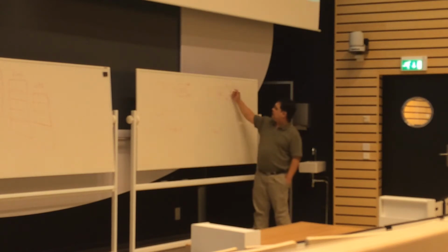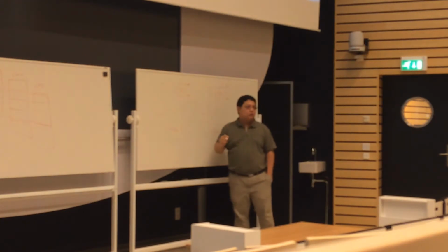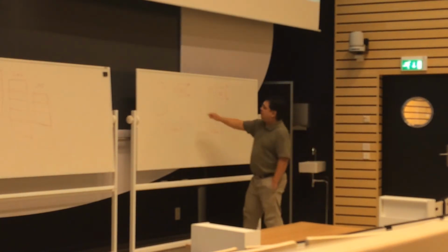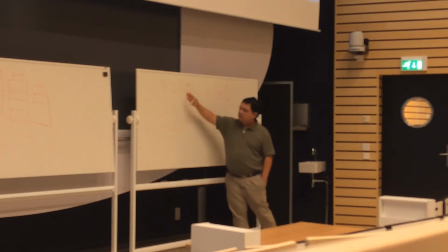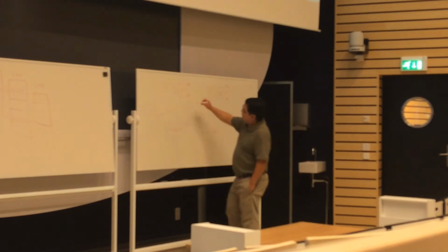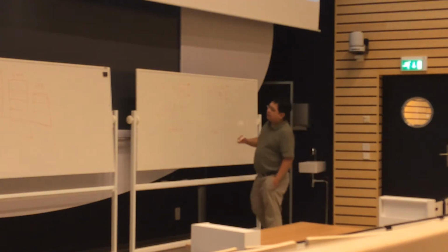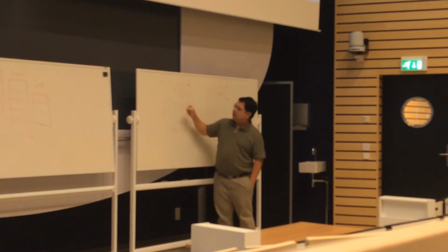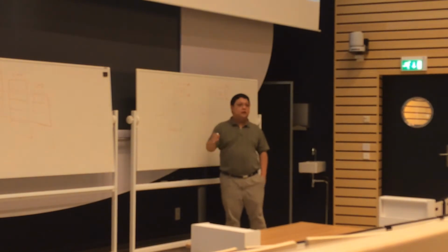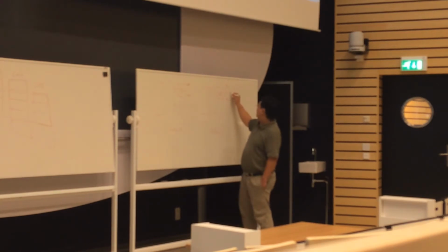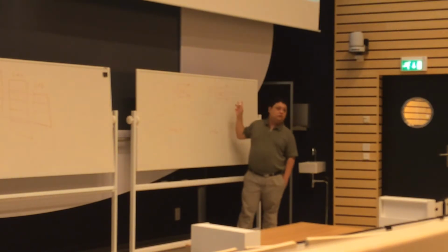If it wants to read something, let's say a register here, then there must be a copy operation. It must send a request to this cluster and say, I want to read this register. And then this register needs to be put somewhere to be able to be consumed by your data paths there. Now, there are explicit copy operations, which means that inside the code it says, I want to read from cluster 1 this register. But you also have implicit copy operations, in which the hardware detects that you want to read register, let's say, 40, and it knows that register 40 is not in this part, and then it will implicitly go fetch register 40.